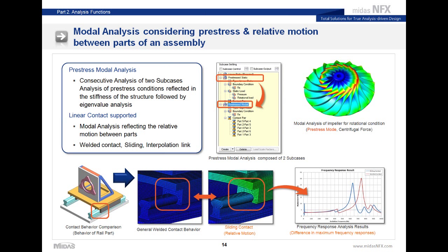The modal analysis in Midas NFX, you can do, for example, using the subcase, you can do the prestress analysis, then you can do the modal analysis. You can use also the sliding contact, as I said. And as you can see in here, when you are doing a frequency response, the results you obtain are very different if you are using a normal sliding contact.